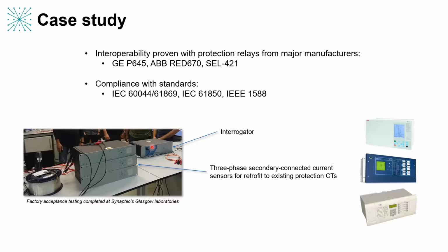And we've even been asked by some customers to provide, for instance, full analog waveform outputs, which is not something we necessarily do as standard, but it is something that we can do, which would essentially result in us providing a remote analog output of each CT at the local substation. So we can really do anything that's required in that area.